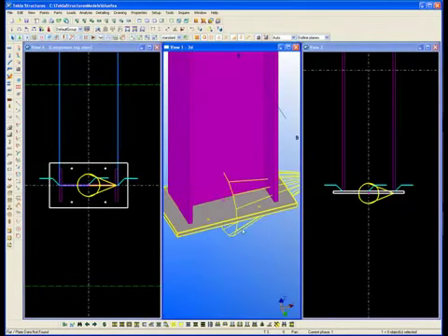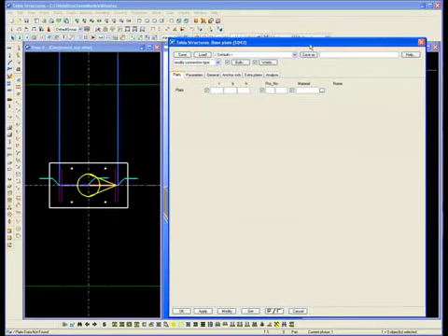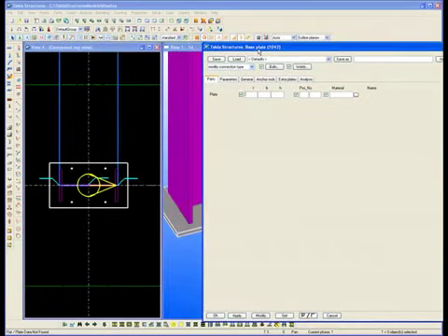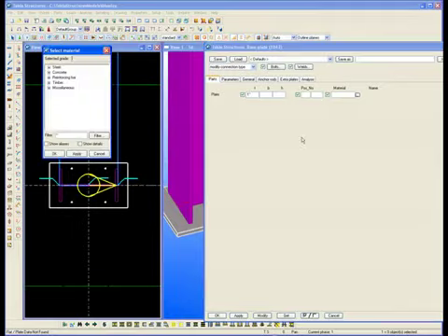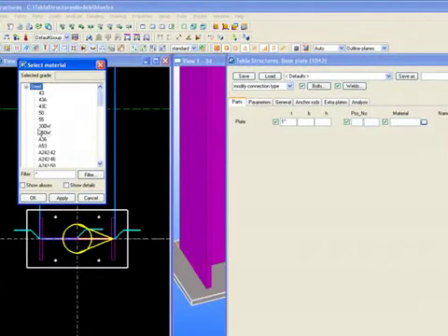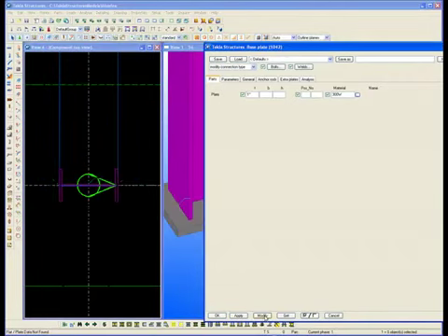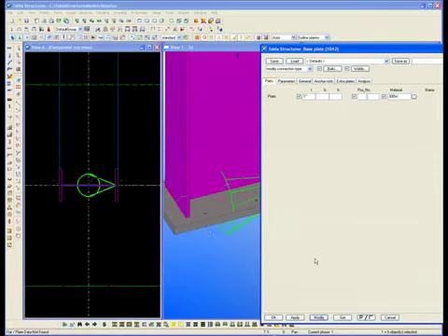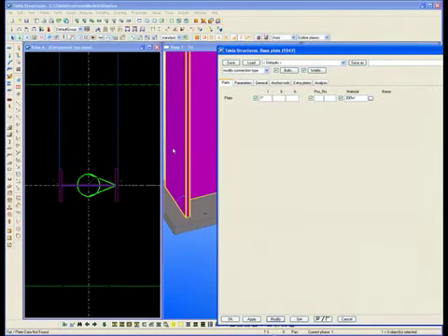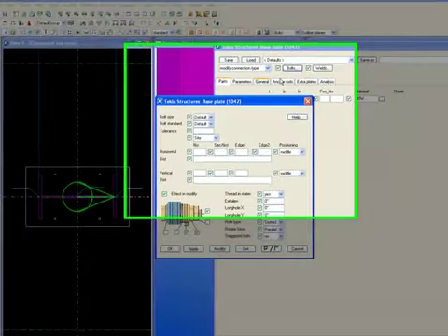By loading the option up, you click twice really quickly, loads up the component. Let's make our base plate 1 inch thick, and for the material, you could pick any material you like. It depends on the job, so let's make it 300 for now, and you can see the base plate become 1 inch. Now let's change the spacing of the hole by going to bolt.